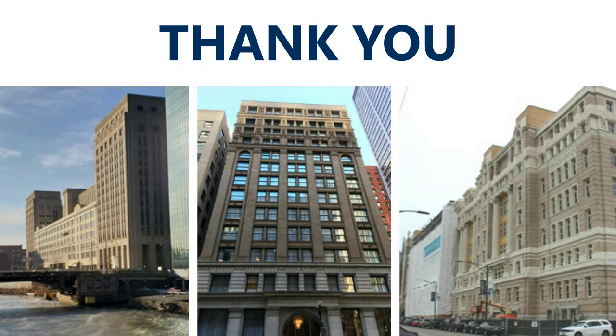Okay, our next question. How do you recommend budgeting for unforeseen conditions? Is there a reasonable standard for contingency? Yeah, I think, again, it depends a lot on the building type. As you do facade repairs as an AE, you learn an idea of the type of distress and conditions you might run into based upon what the building is, how it's constructed, and how large the project is. There's usually a percentage for contingency, and it's discussed early on with the owner.